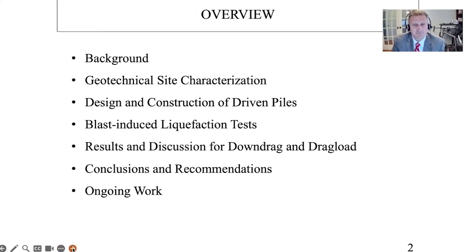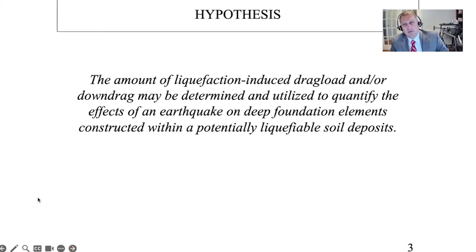So looking at this, the hypothesis is that if liquefaction happens, there will be some down drag and drag load that develops. The site that we're looking at in Arkansas has a clay cap. So the top 20 feet roughly are clay, and then there are liquefiable sand deposits below. And so we wanted to investigate what happens if liquefaction does occur. Does the clay on top grab onto the pile and cause drag load to develop? And then also, what's the influence from the down drag that happens with that?